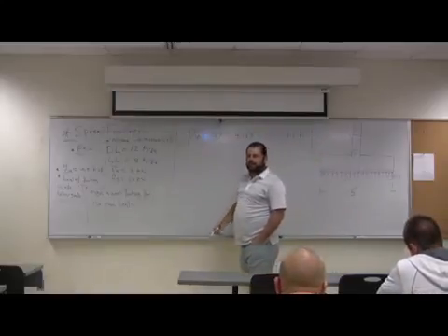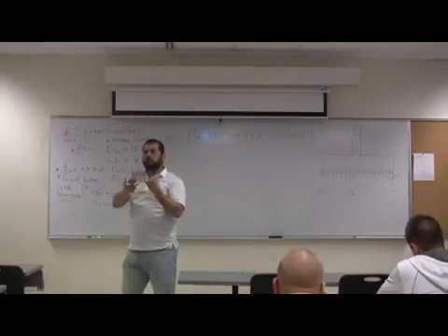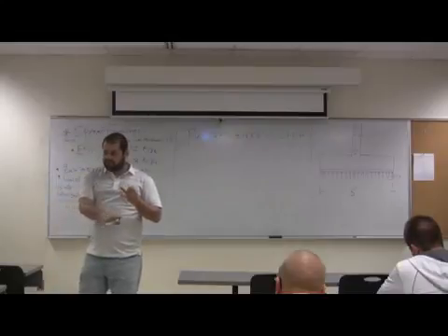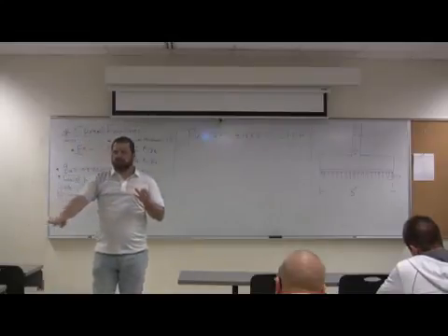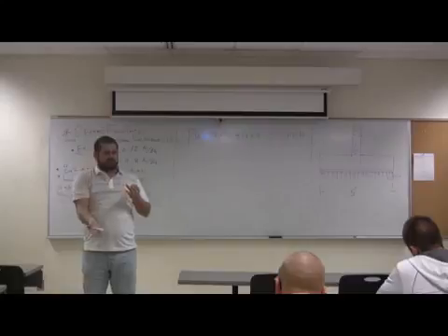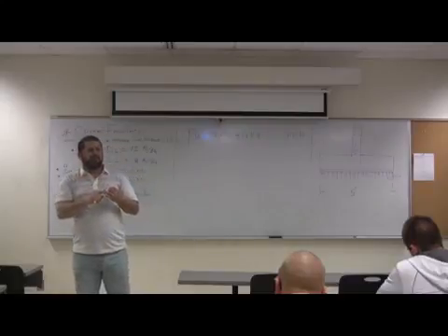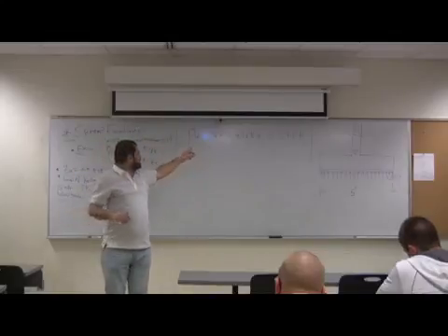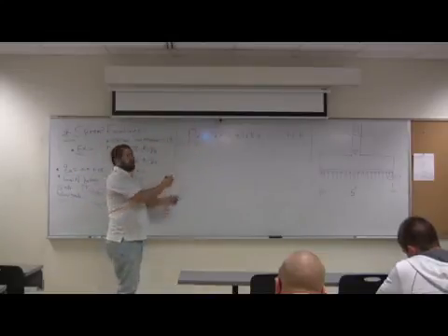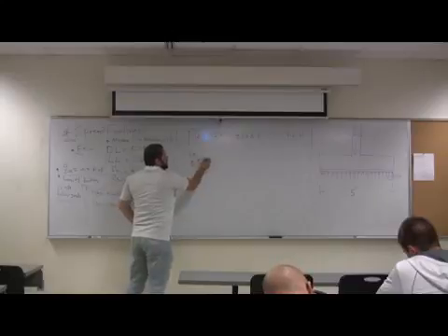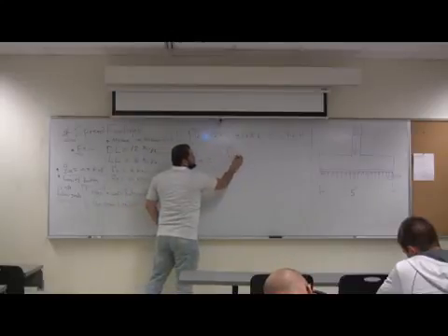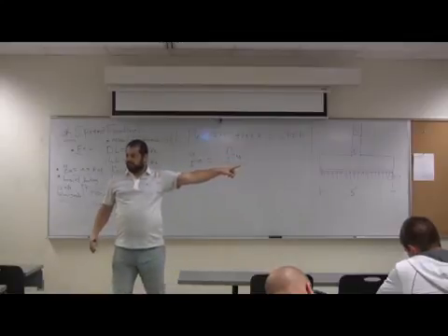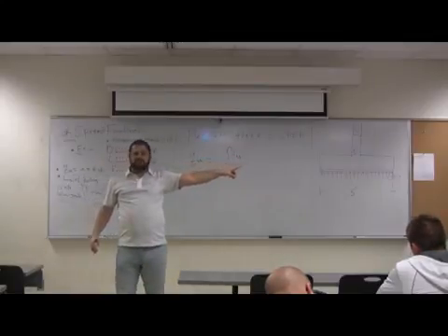Now, what do we do? Now remember, so far we have 2 Q's. Q allowable from the soil guide, and Q effective at the level of the footing, subtracting the weight of the soil and the self weight of the footing. Now we need a Q for strength design. We're going to call it Q ultimate. And Q ultimate equals P ultimate divided by the actual area dimension you use.